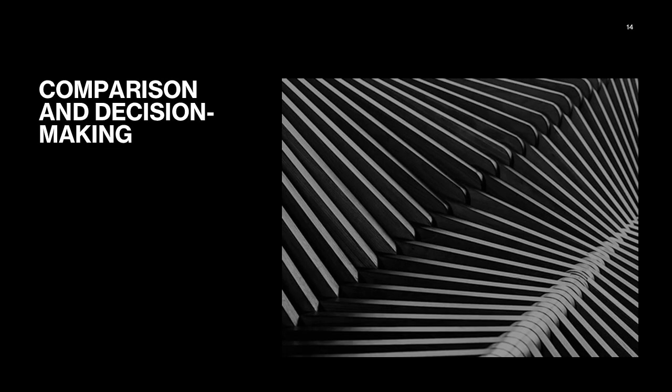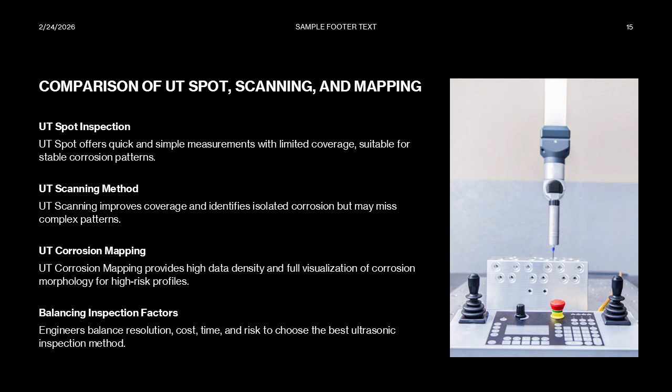Comparison of UT spot, scanning, and mapping, decision criteria and practical applications. UT spot, UT scanning, and UT corrosion mapping form a tiered approach to ultrasonic inspection, each offering different inspection resolutions, costs, and coverage capabilities. UT spot provides the quickest and simplest measurement method but offers limited coverage and may miss localized thinning. UT scanning increases coverage and helps identify isolated corrosion mechanisms but still may not fully capture complex corrosion patterns. UT corrosion mapping provides the highest data density, enabling full visualization of corrosion morphology.